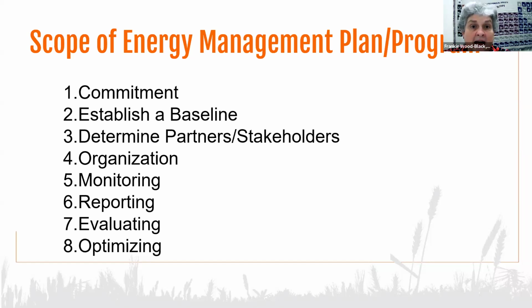You also have to know where you're at. Where are you starting from? How are we going to know if we've made progress? So we've got to establish that baseline. And how we do that with an energy audit is we go back and look at those utility bills over the last couple of years, see where you're at. What kind of equipment do you have? How old is your equipment? What kind of energy does that equipment operate? All of those things are really important.